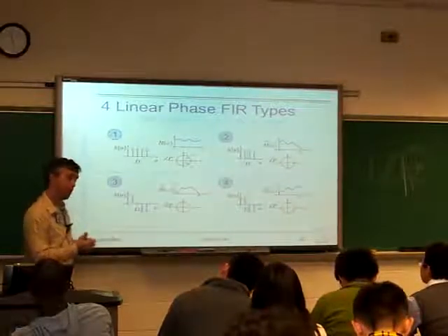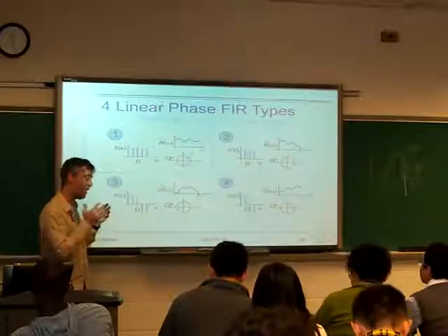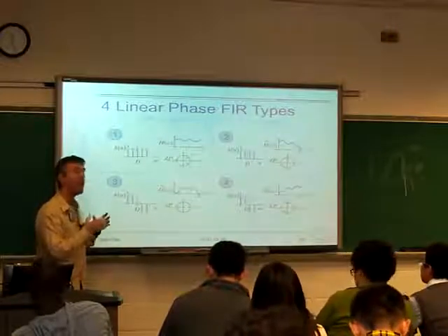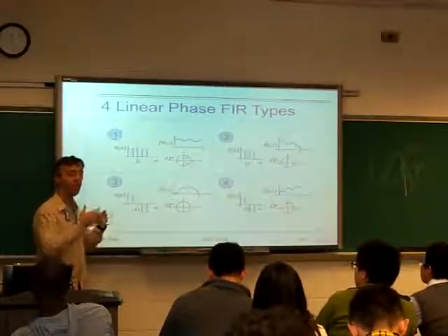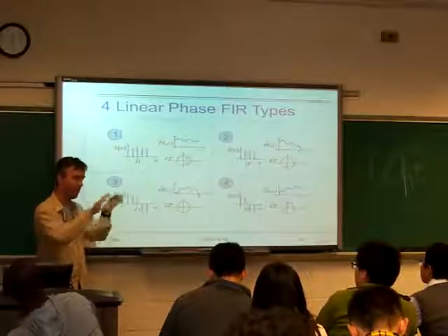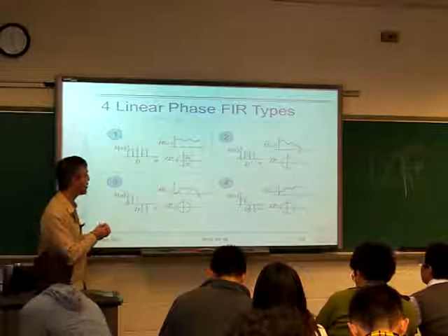And yeah, we have our ideal phase response that the delay experienced by all sinusoids is the same. And so the shape of the function, which is the composition of the different sinusoids, is not distorted as a result of that.